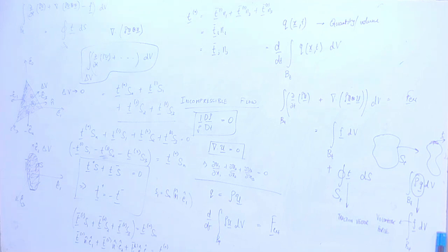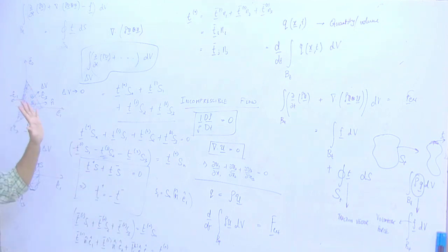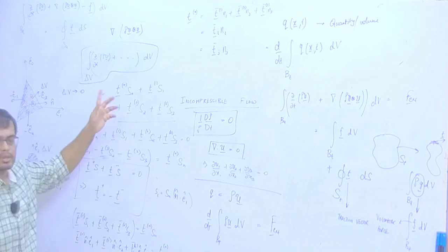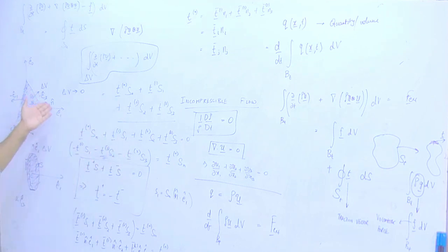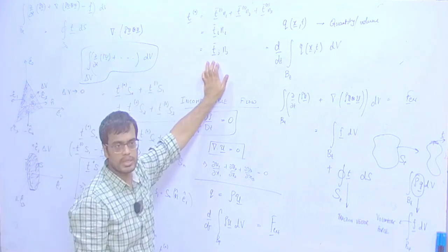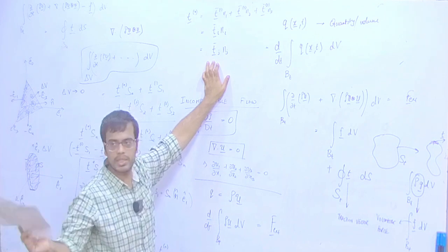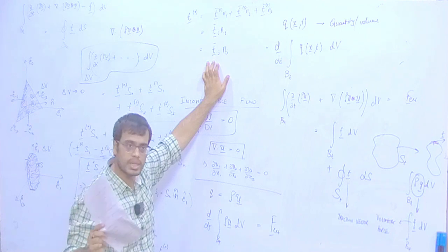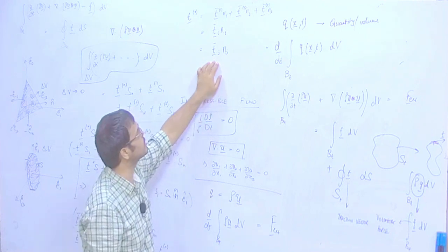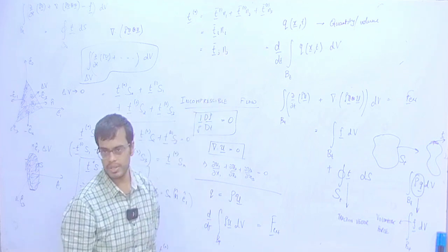The important point here is that the traction vector on an arbitrarily oriented surface, which is this n vector Tn, you can write as a linear combination of some traction vectors, let us not bother about the physical significance of those traction vectors, times the components of the normal of that surface.